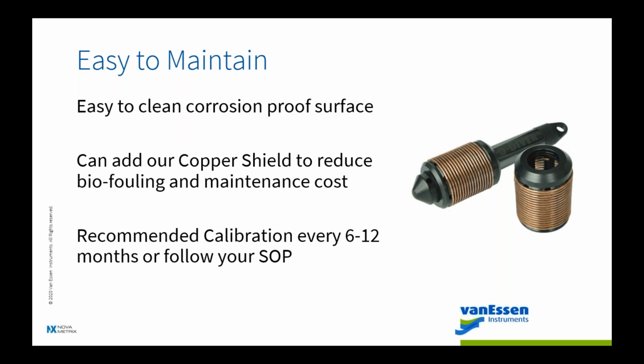Something else that can keep the units, certainly the C cells, from biofouling is adding a copper shield. This copper shield can be purchased separately. It slips over the back of the diver and onto the C cell, and significantly reduces the maintenance visits to site and the maintenance costs associated with that. We had one client in Florida that was going out every 6 weeks because it was getting gummed up with some form of algae.